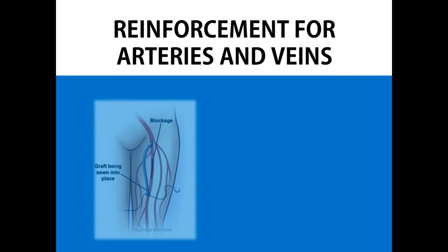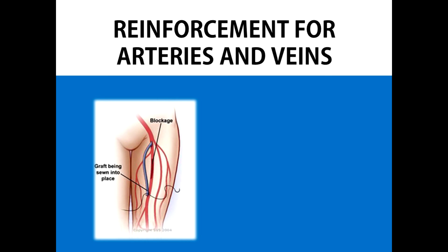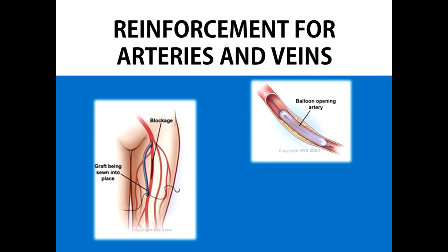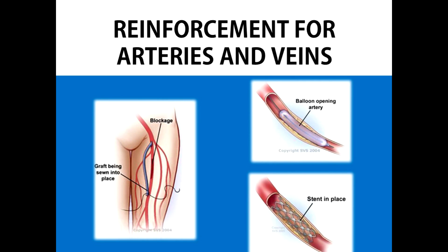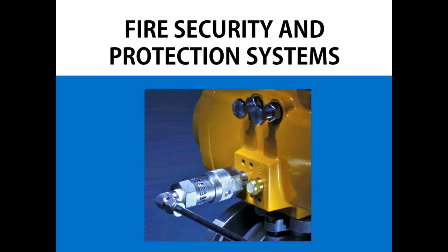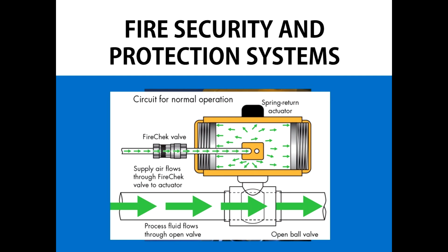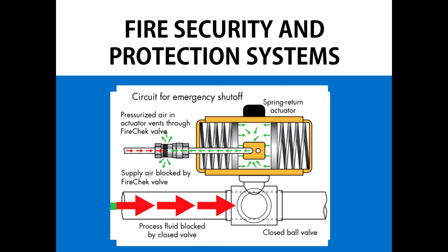For clogged blood vessels, an alloy tube is crushed and inserted into the clogged veins. The memory metal has a memory transfer temperature close to body heat, so the memory metal expands to open the clogged arteries. Lines that carry highly flammable and toxic fluids and gases must have a great amount of control to prevent catastrophic events. Systems can be programmed with memory metal to immediately shut down in the presence of increased heat. This can greatly decrease devastating problems in industries that involve petrochemicals, semiconductors, pharmaceuticals, and large oil and gas boilers.